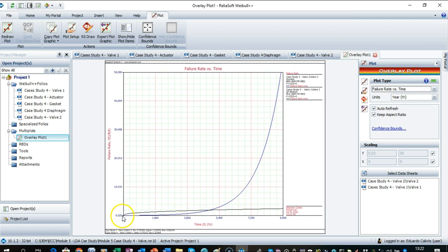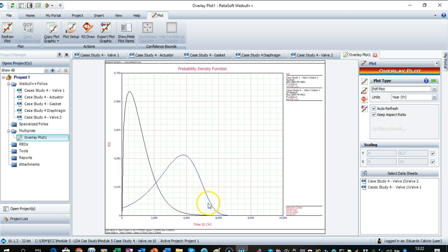Based on the first case, since I have an almost constant failure rate, I will define some reliability to make inspection, and that forces me to make a lot of inspections. But based on the proper prediction, I will do inspection after 1.8 years or something around here to detect failure. And let's take a look at the PDF for these two different organizations. It's totally opposite.